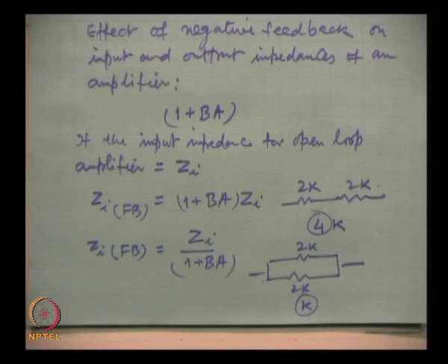So, remember this basic fundamental. We derive an expression for the input and output impedance. I take just one example each at the input and output, and similarly the analysis can be done for all the 4 circuits, because we have to devote time for other things. So, all the 4 analyses are not required to be taken, but as an example only one I take, that is voltage series negative feedback.